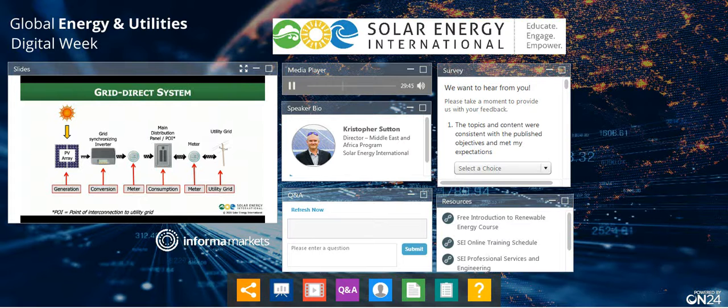We have an inverter that only produces AC power when it's synchronized with a utility grid. So when the utility grid fails, if the grid goes down and we lose our AC supply from the utility, our inverter is also going to go offline. These inverters are designed to not push voltage into a dead utility line. And we don't have any storage anyway. So this system is designed to shut down when it loses AC power. Now, that's a safety thing, of course.